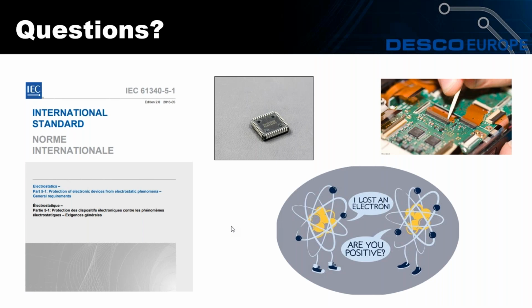The way it works is that it's a power strip that is relay controlled. So the idea is that until you have connected your wrist strap, the bench won't electrify. You can imagine all the things that you require to be switched on: your ioniser, your lights, your soldering iron, your fume extraction. All of that would be connected to the power strip, and then the power strip is only activated once the wrist strap is connected. It's that type of solution. So we'll send you more details on that, but just to note that it's currently in development for Europe. We're doing research into putting that in play.